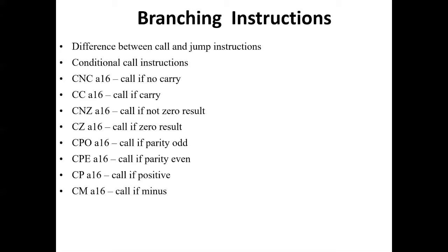Next is CC A16. CC is a mnemonic which stands for call if carry. This instruction is used to branch to the subroutine whose 16-bit address is provided in the instruction only if carry flag value is 1. If carry flag value is 0, program flow continues in the main program sequentially.